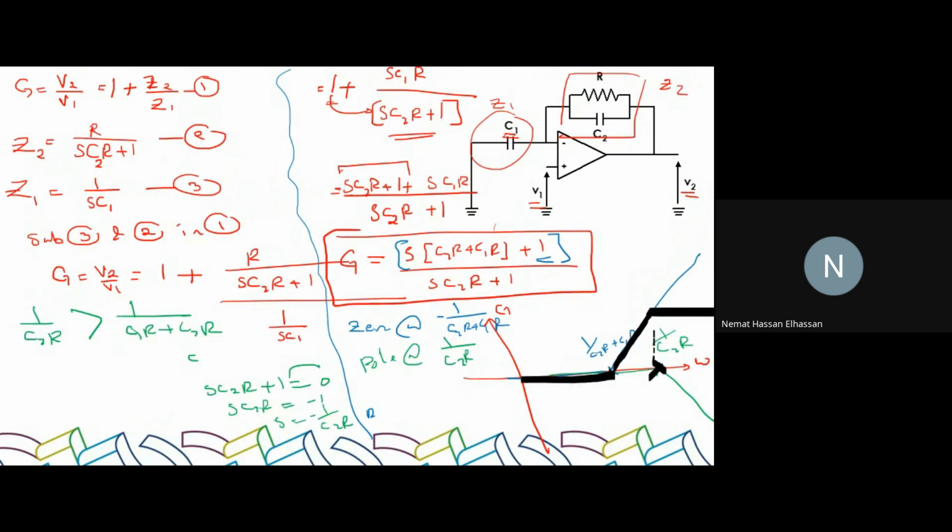طيب, if you look at this black transfer function, or if this is frequency and this is gain, what type of filter does this implement? High pass filter. So this circuit implements a high pass filter. So when I ask you the exam question of what type of circuit this circuit implements, you have to do all of this calculation and then this plot and then say this circuit implements an active first order high pass filter.